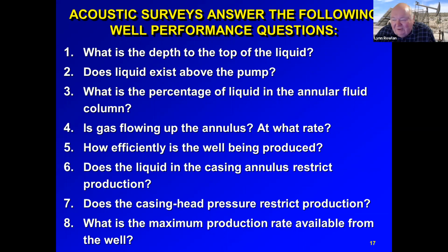And then based on the producing well pressure and the current liquid production rate and the reservoir pressure, we calculate the maximum production rate from the well. If you could draw the bottom hole pressure or pump intake pressure to 0, well, you probably can't get that low, but it gives you an idea how much fluid you should be able to get out of your well.